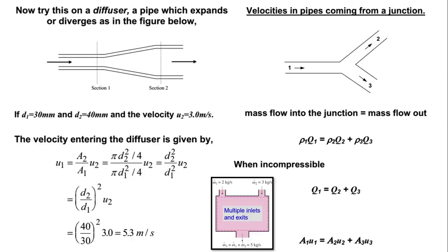Okay. So, similarly, when you've got water coming from a smaller pipe to a bigger pipe, it means we've got higher velocity, and on this side you are going to get lower velocity. So when you do your calculations, if you find the velocity here is lower than the velocity in section 2, then just know that you have made some errors and your answer is wrong. Under normal circumstances, a smaller area should correspond to higher velocity, and larger area should correspond to lower velocity at the end of the day.